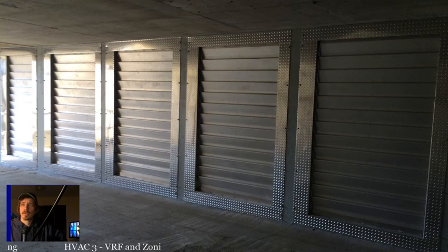The normal, alright, this is something we didn't go over either. The normal water temperature on a chill water system that's used for comfort cooling, okay? The normal temperature of that water is 55 degrees. That's the return water temperature. The outlet water temperature could be 35, 45. It depends on the delta the system was designed for, what everything's designed for. But generally, the returning water is going to be about 55 degrees.